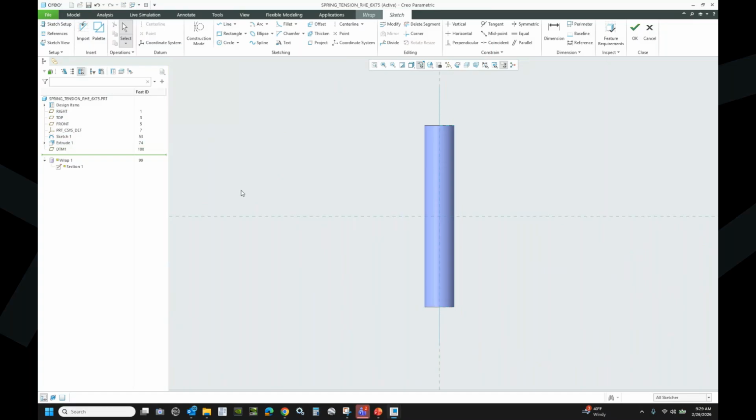And then we're going to create a construction coordinate system. Now, I'm going to put it right here, and I'm going to make the y-axis be vertical. This is required in a wrap feature. Like I said, we're going to create a sketch or a curve that's going to wrap around the cylinder. You have to think of a wrap feature like putting a bumper sticker on your car, where you kind of use your thumb to hold the corner down, and then you spread the bumper sticker.